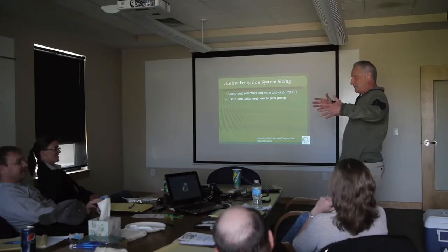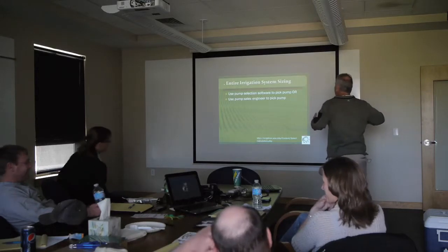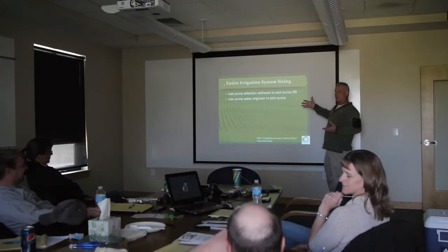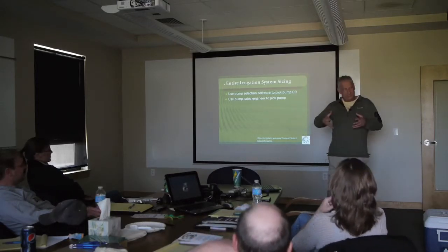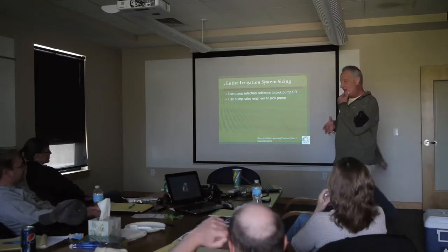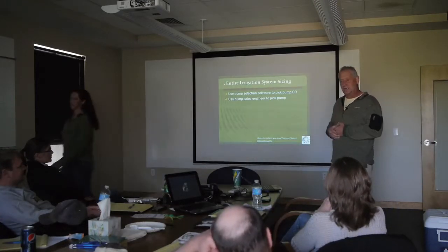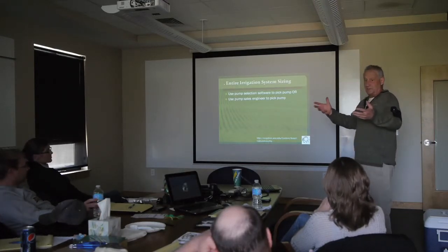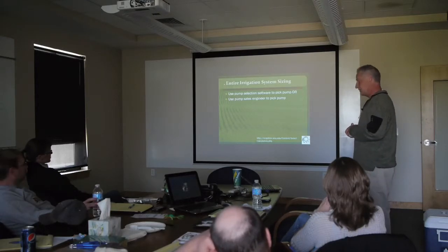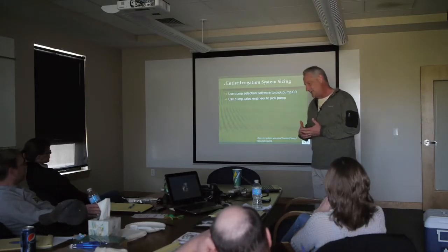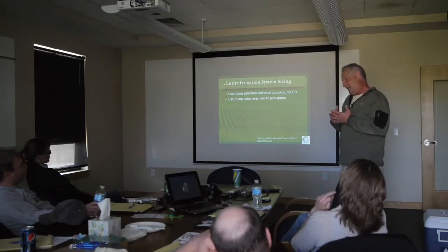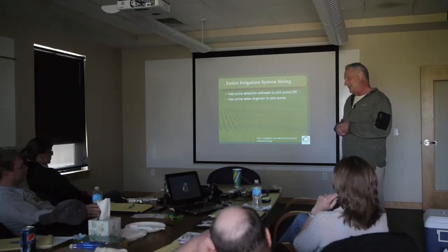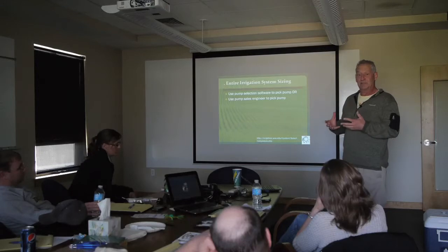So then you know what the pump is, you know what the pump should be, so at that point you can use the pump selection software to pick the pump. The manufacturers make different software, or you can ask the sales engineer to pick the pump. He hopes to sell a pump someday, he can help you do that. So, if you have an existing pump, you're doing an energy audit, then it's going to help you understand, is the pump too big or too small?